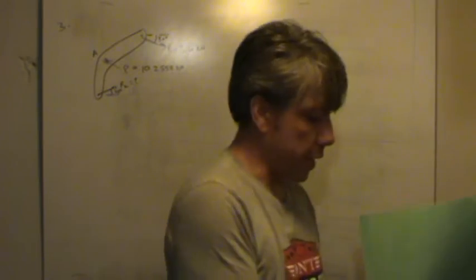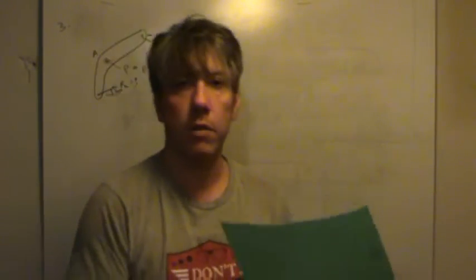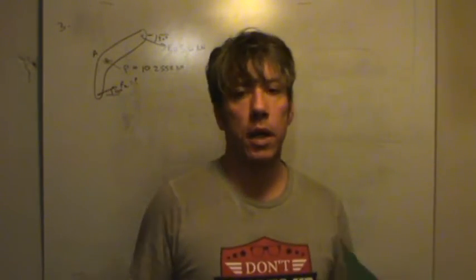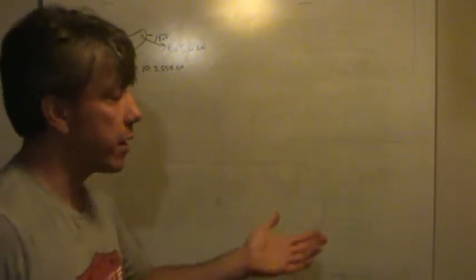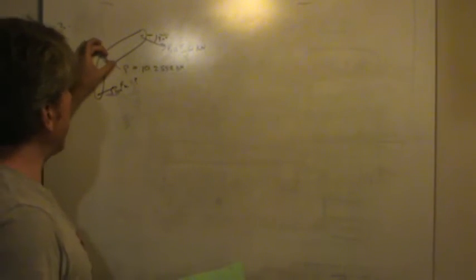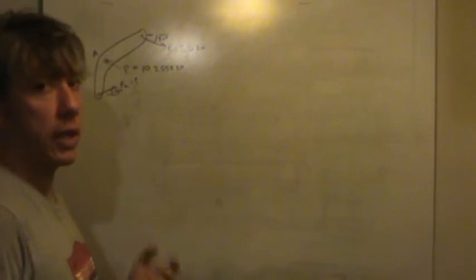So now we finally get into strength of materials. Now, in looking at this problem, when I first looked at it, I was a little bit confused. I hadn't really noticed the section, and I just thought, oh, this is an interesting combined loading problem, or, well, two different areas to analyze, basically. Notice they did not give us the thickness of this link, and so I thought, well, I could size the diameter based on shear, and then I could size the thickness based on bearing stress. Well, they didn't ask for bearing stress, but I went ahead and did it anyway.